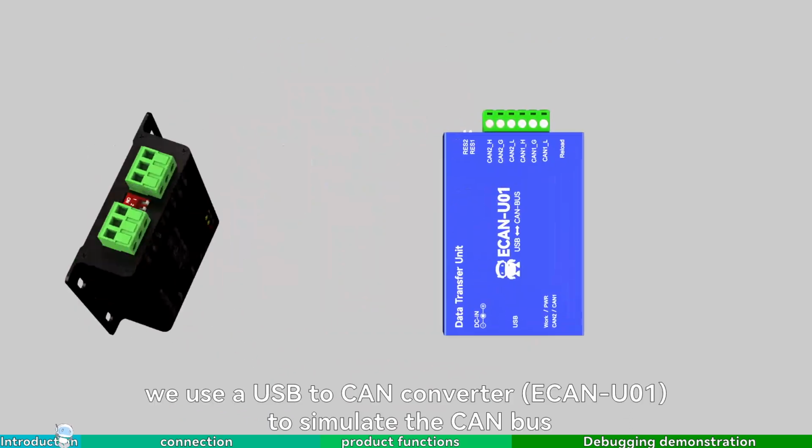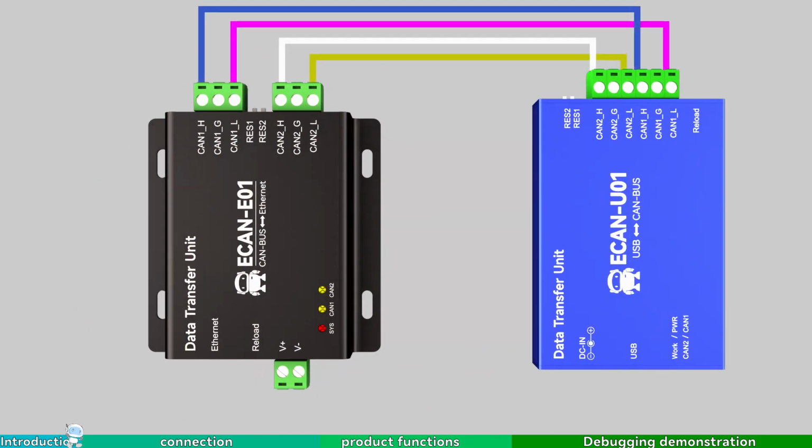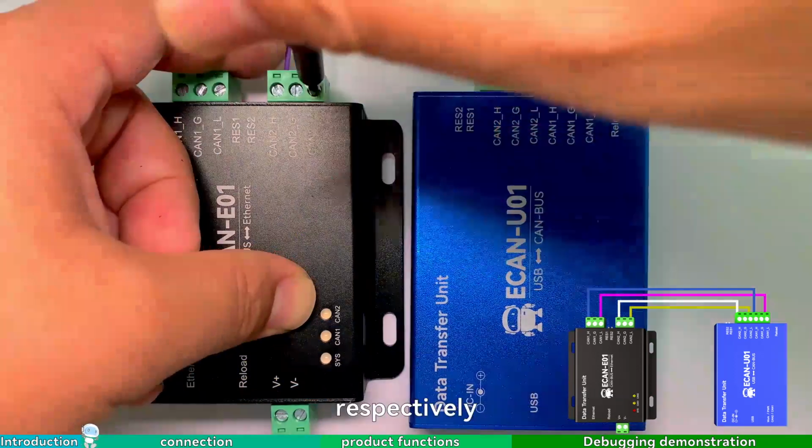For this test, we use a USB to CAN converter to simulate the CAN bus. Connect the CAN L and CAN H of Ecan E01 to the CAN L and CAN H of the CAN bus, respectively.